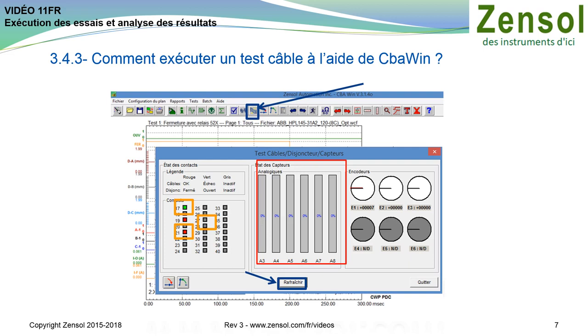If the condition of the contacts is abnormal, check that the clamps are correctly installed on the contacts and that they are clean to ensure good adhesion. If this persists, change the input cable and see if the color changes channel. If so, your cable may have a problem.